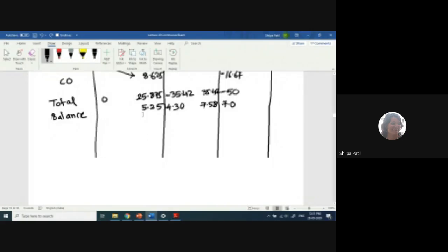Now the moment from B to A will not get carried over because A has a simple support. So carryover will happen between B and C only. So I have to carry over this moment with a half value to C. Similarly, carry over this moment with a half value to B. So tell me half of 4.3. 2.15. And half of this, 3.79. Okay, this is the carryover.